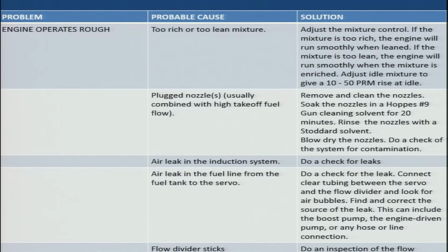If the flow divider sticks, in that case we need to inspect the flow divider installation for looseness and any physical breakage. In case not, we need to replace the flow divider, because we are not supposed to do any maintenance in the field on the flow divider.